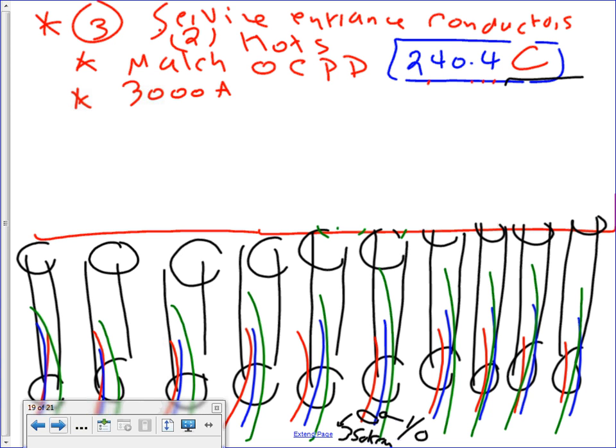The concept of paralleling, guys, is to have 2 conductors. This conductor can carry 100 amp on each phase. You tie them at the end like this. So 100 plus 100, 200. Now this system is 200. Say I need another 100, I grab another conductor in every phase and tie it at the end. They call them parallel. Here's the circuit breaker, here's the load, tie them at the ends. Now each one of them is 100, so the total would be 300. Everybody understand what parallel conductors are? We use them all the time.